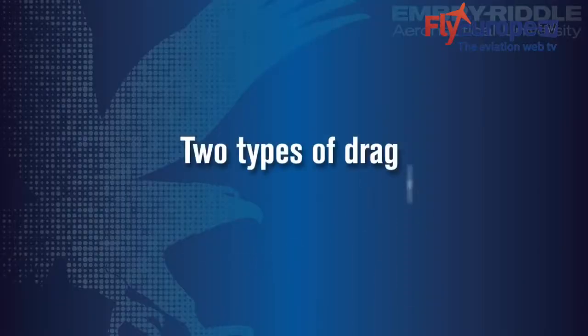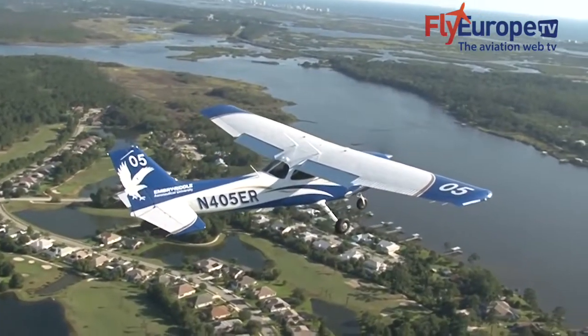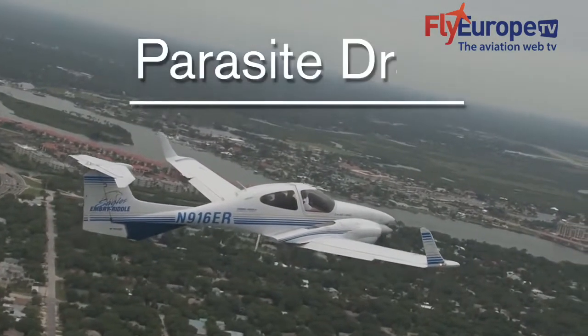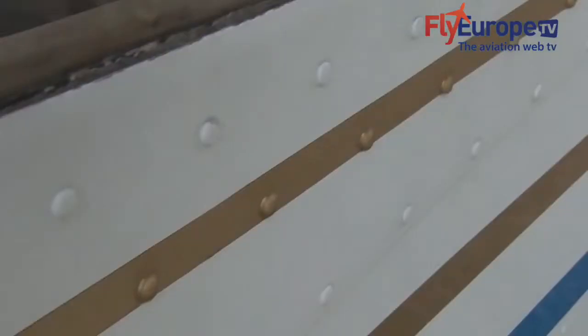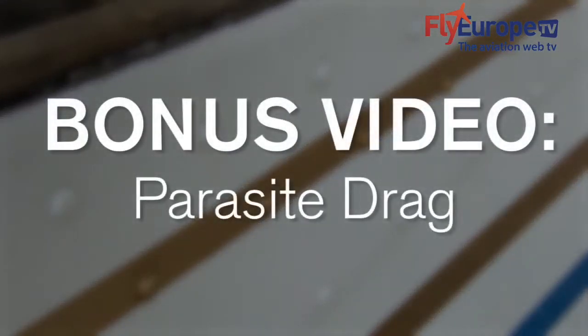There are two types of drag, parasite and induced drag. Parasite drag is a direct result of the air resistance as the airplane flies through the air. There are three types of parasite drag: form drag, interference drag, and skin friction drag. To learn about these three types, check out the bonus video on parasite drag.